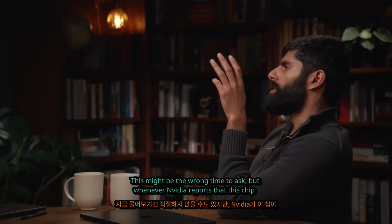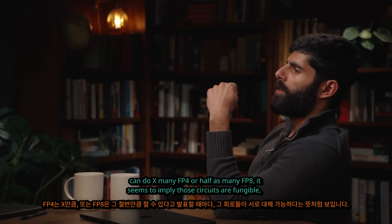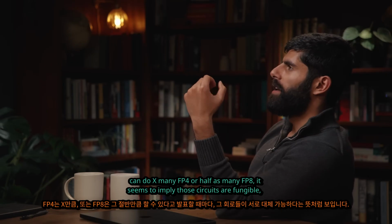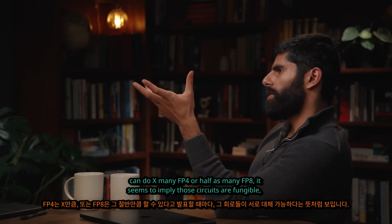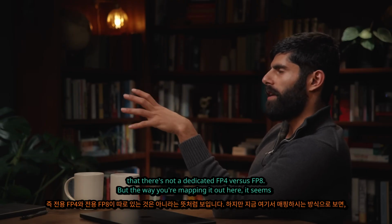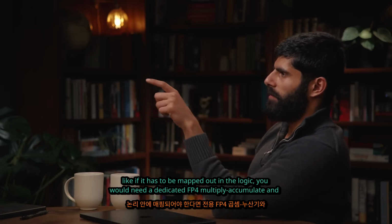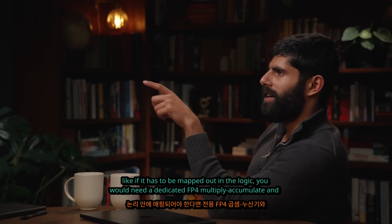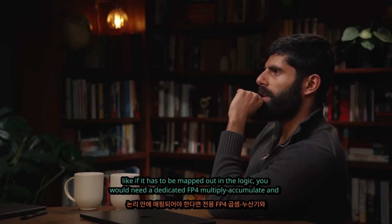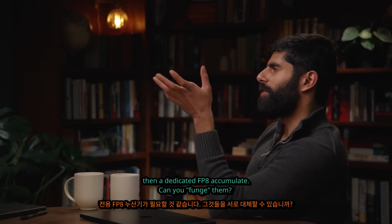This might be the wrong time to ask this question, but whenever NVIDIA reports that this chip can do X many FP4 or half as many FP8, it seems to imply that those circuits are fungible, that there's not a dedicated FP4 versus FP8. But the way you're mapping it out here, it seems like if it has to be mapped out in the logic, you would need a dedicated FP4 multiply accumulate and then a dedicated FP8 multiply accumulate. Basically, can you fungibly share them?